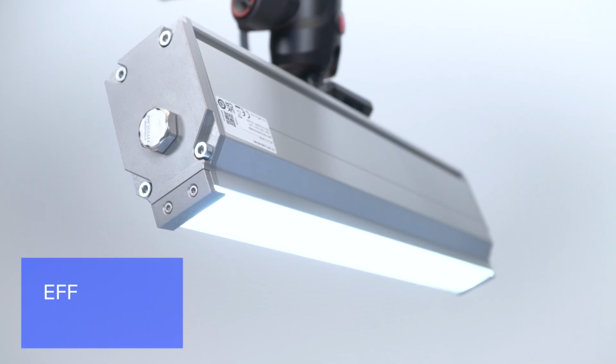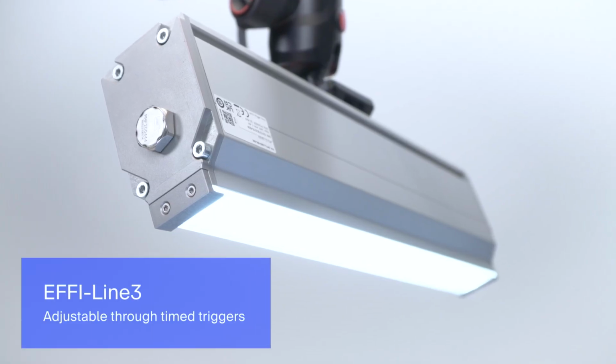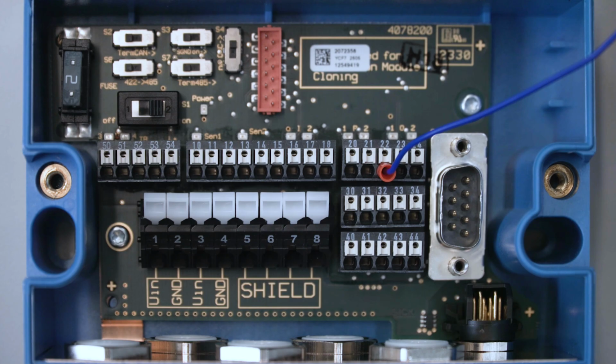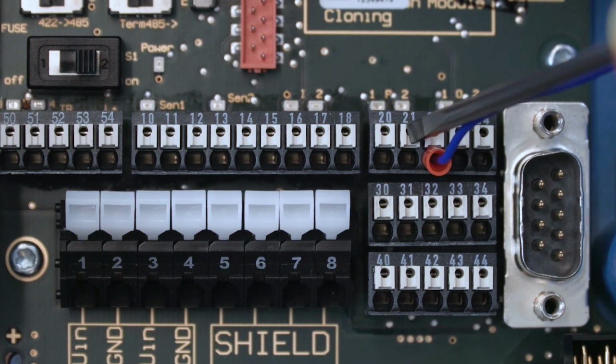The next step is to set up the external light. The Surface Plus technology can be used with various lighting sources depending on what features you want to enhance. It is important that the light strength is adjustable, either through timed triggers or by setting a steady analog level. The light we use in this setup is adjustable through timed triggers, and we will utilize the camera output Laser Strobe 2 to control the light. If you are using a CDB connection module, Laser Strobe 2 is located at pin number 21.